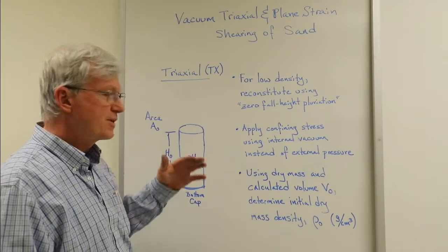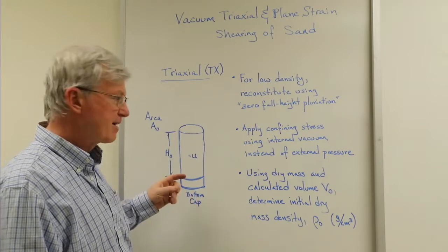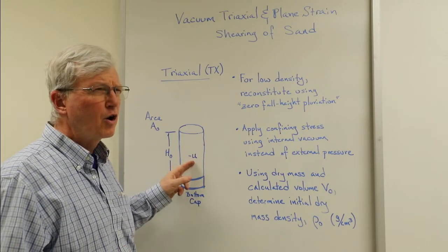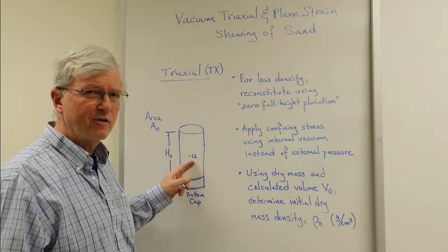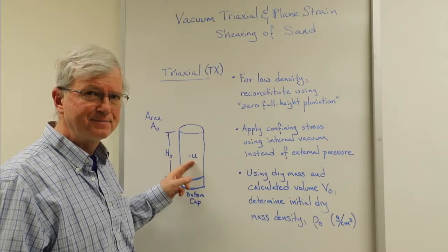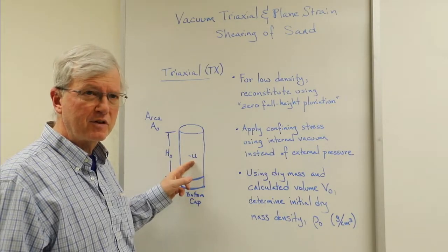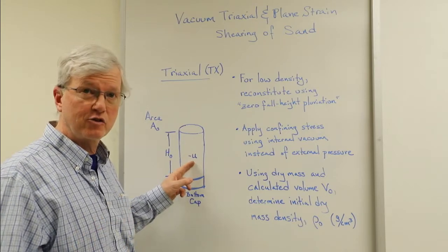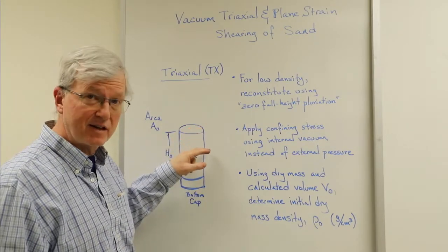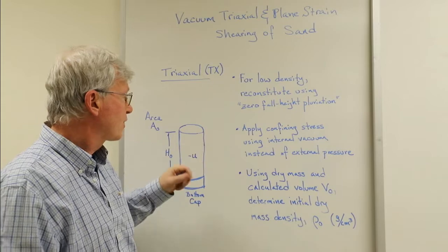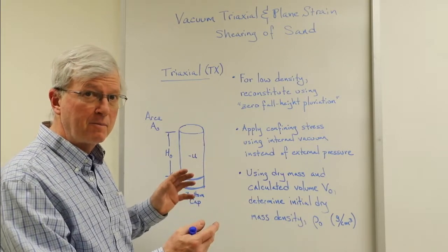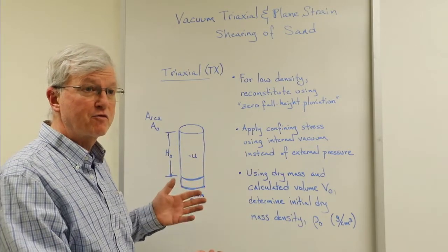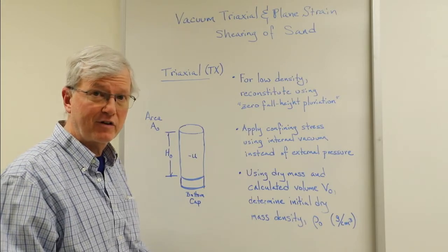And so as we shear this specimen and apply a constant vacuum, are we thinking this is a drained test or an undrained test? People talk about those a lot. When you have a specimen like this, as you'll see, we're going to have compressive strains. We're going to have some bulging, but there's nothing about the system to prevent the soil from changing volume.